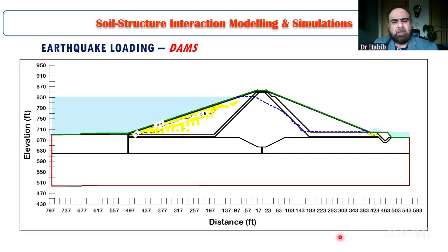And once it is done, we can have, for example, a precise evaluation of the liquefied zones, or where the liquefaction has taken place. So this model can give you all this information through one SSI modeling alone. So this is how earthquake modeling has transformed into a new era, where real earthquake can be loaded on the structures, and we can get the real response, or real-like response from these structures.